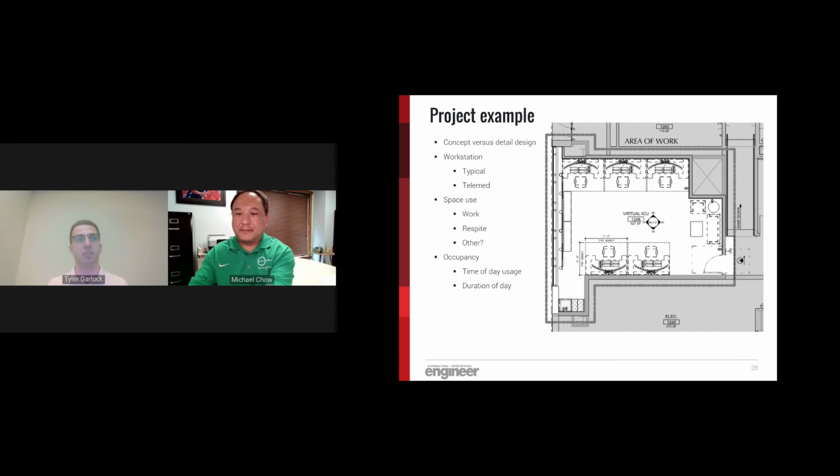So in thinking about the design, it became very obvious that downlights probably were not the best option in this facility, given the fact that the workstations are facing the wall. So the can lights would either be above the person or behind the person, which would cast shadows for the doctors that are on these telehealth visits. Which would make it hard for people who were calling in to get health advice to see their face. Not only is that a problem just in general, but if you think about people that might be calling into these, they might be visually impaired or hearing impaired. So it might be very important that the people working in these spaces have light on their faces.